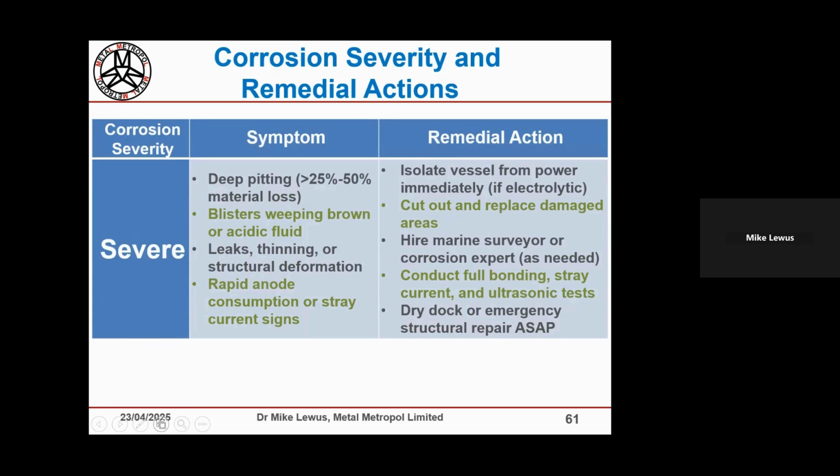Severe, I mean, depending on your level of knowledge, it could just be an area where you do have to find someone who's more expert than yourself, particularly if it's a structural part. If you've got osmosis on a GRP hulled yacht, it's not an easy matter to correct that. If it's at a level where you've got to start cleaning off remnant gelcoat or removing affected GRP material, the laminate, well, it's a bit of a specialized area to restore that.